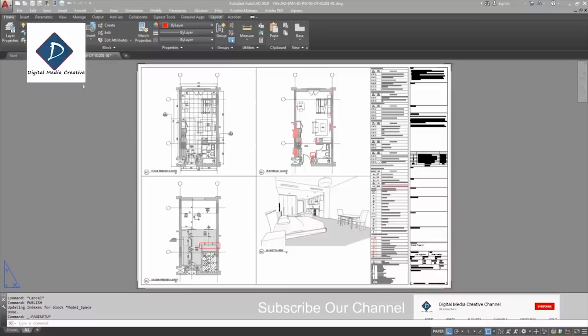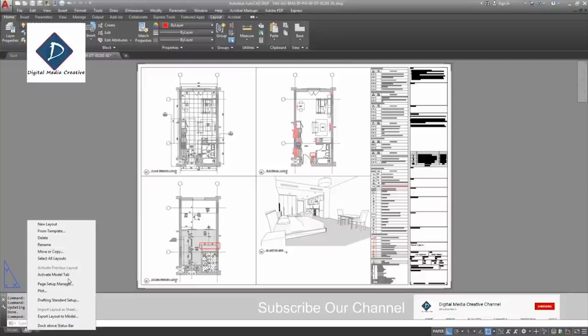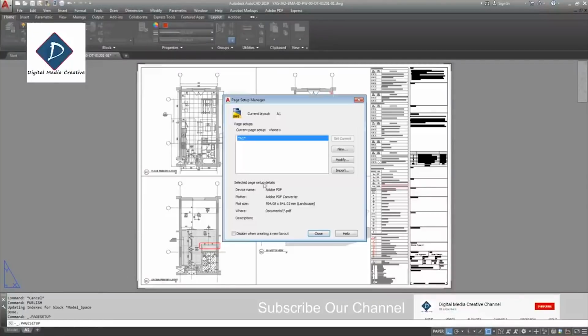So I just open, then you can go to the layout, make sure you click the Sheet Set Manager. Then here, for now I'm just showing how to export PDFs only, and the same way you can make it for DWF or print or anything.